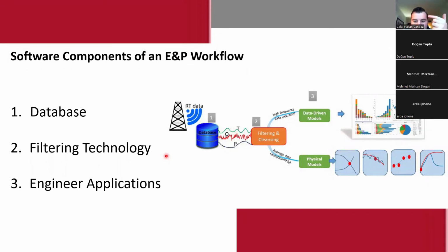Okay, so the filtering process is programmed to remove what? Erroneous data and outliers and provide representative values for the data during the time period of the evaluation. Okay. So when the data is received, cleaned up, and post-processed, the main output is an average value of the raw data. That's actually the production rate, for example, Q, the production rate, pressure, and temperature values at a specified frequency.